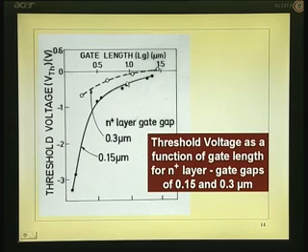That is the circuit engineer's practice to get the threshold voltage. So, when you do that, the threshold voltage becomes more and more negative as you go to shorter channel lengths, keeping the gap at 0.3 microns and reducing the gate length. In other words, what is happening is that I think I had better have the diagram here now.